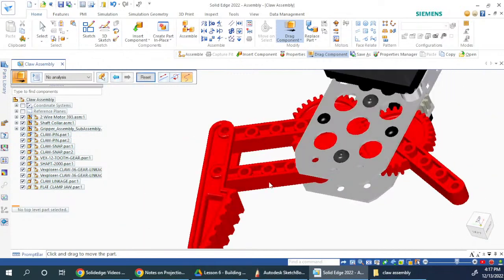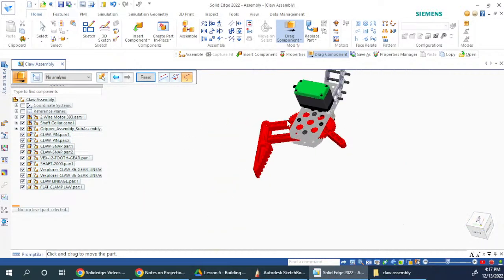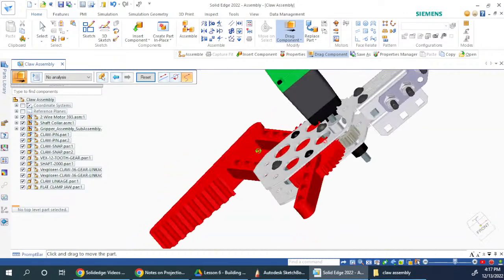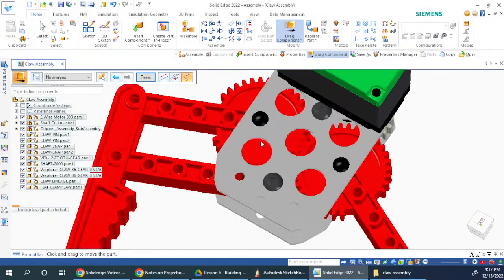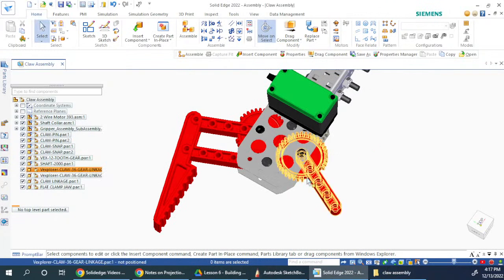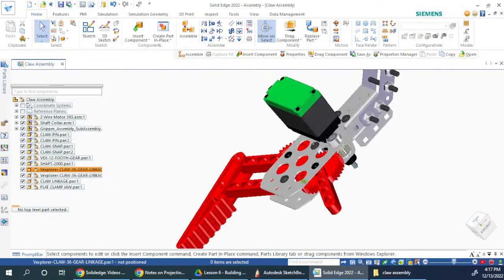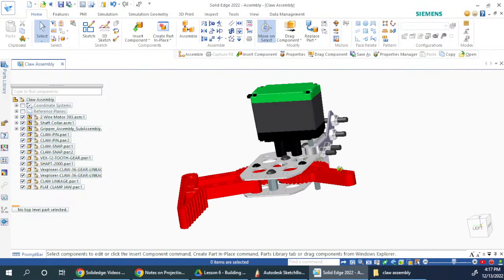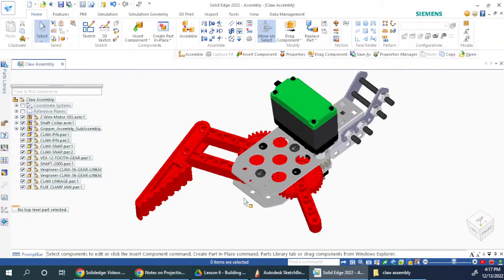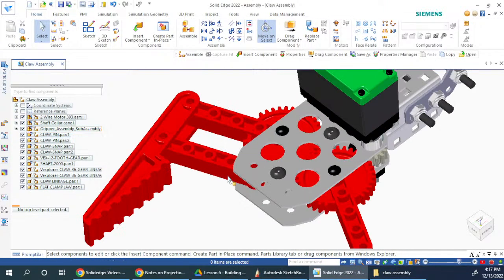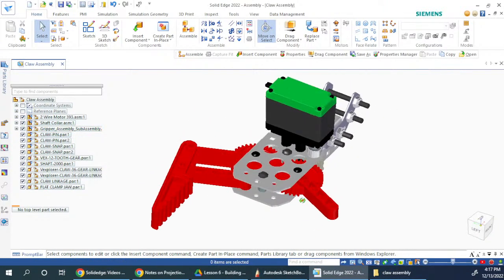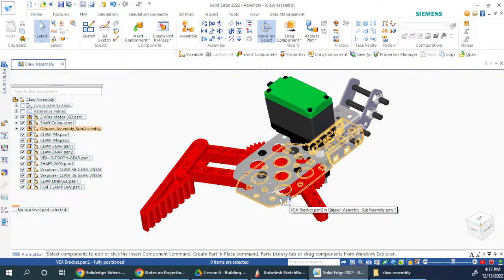Right, fine, perfect. So this is now working perfectly. So you just need to insert 2 more parts like this on the other side and assemble them properly for this to work perfectly. So from here, I guess you can do whatever other things are explained in the video. So I'll just stop this video here, because this was our primary purpose. Fine. So I just wanted to explain how to import this file neutral formats that were created for use in the older version of Solid Edge.